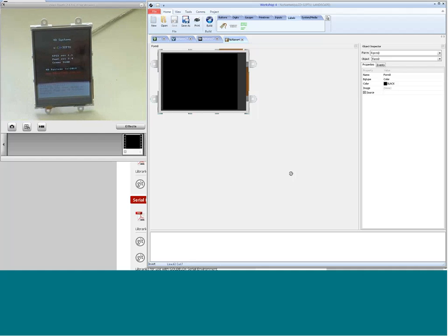And with the PLC, for some, you just need the display. You don't need the PLC. Just make optocoupling, protect the display from the harsh environment, and you're good to go. Like, you can just have a button which triggers an I/O on the back of the display, just without using any other host.